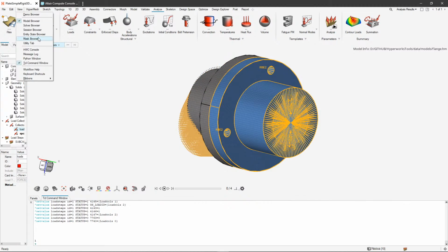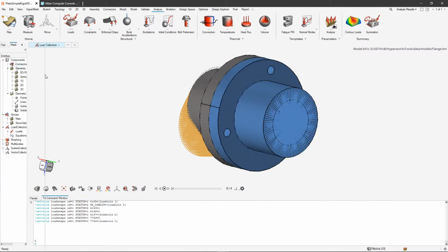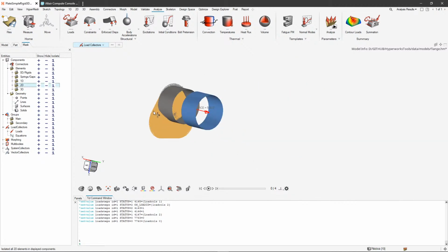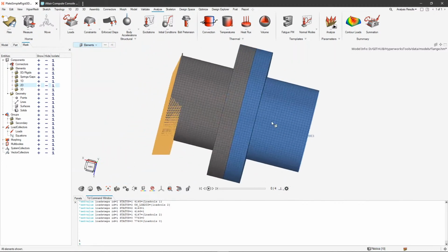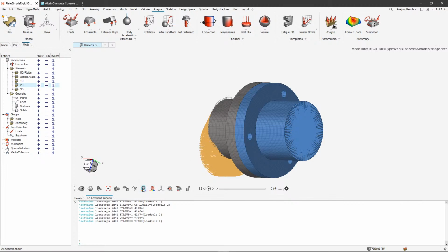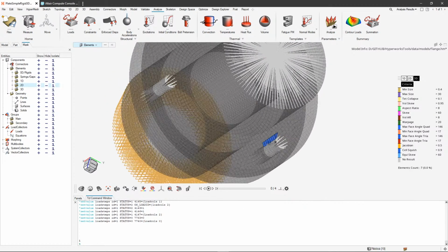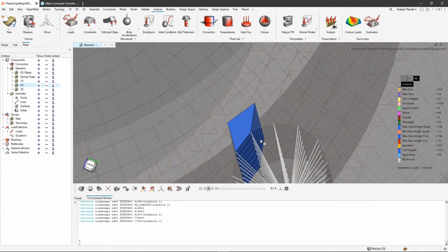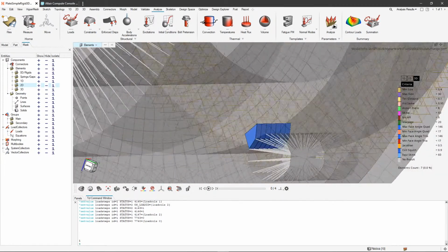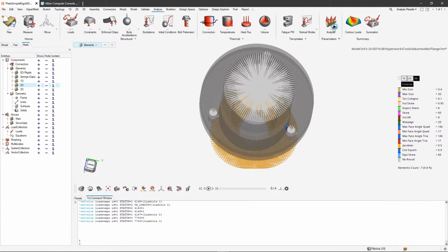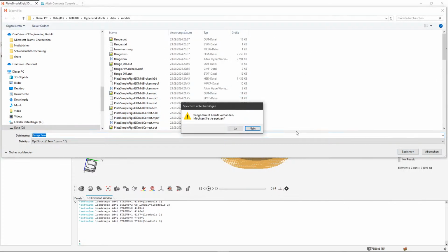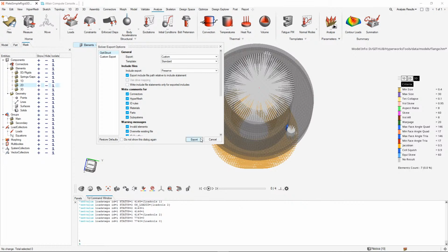That means I have to go to the view and then the mask browser, to see the 2D elements only, then make an element selector and delete the elements. Then just have everything displayed again. By the way, I did not check the element quality, stupid mistake again, but if we have a problem with the element quality now, I will just suppress the element quality check. I think that's okay, right? This hopefully will not fail. But if it's failing, then I will just deactivate the element quality check for now.